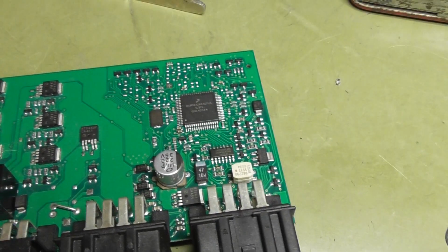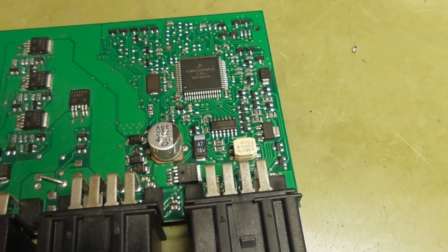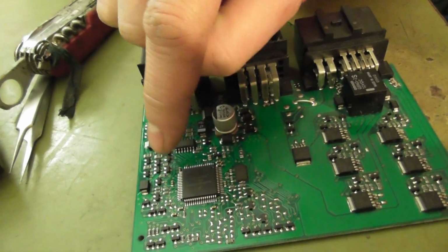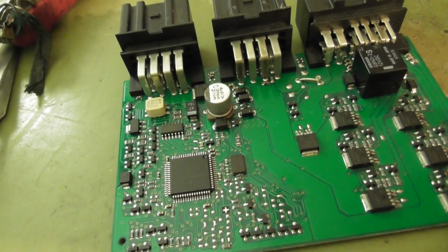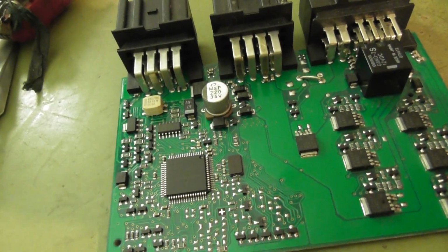Something with this reset circuit on the PCB is wrong. But what? We will find out. To understand what happens here: if you press the reset button on your home computer, maybe the system permanently resets and has no chance to boot up. This is the same thing that happens here. Something permanently resets this controller, this Motorola, and in this way the processor has no chance to boot up.